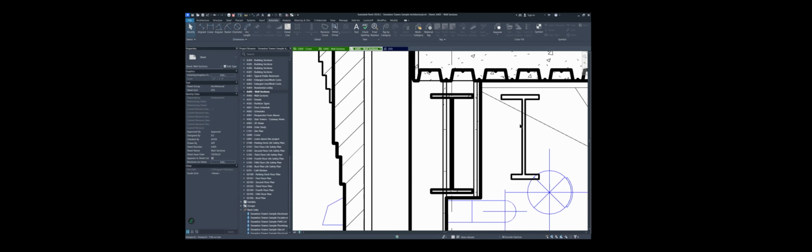So for example, let's say I wanted to put in this I-beam. I could put in a 3D model of this I-beam, or I could draw this I-beam using detail line, as you guys said. So I could go to detail line and literally draw an I-beam. This I-beam is not a 3D object, it's just a 2D object that lives only in this view. But then why draw this I-beam when I have a detail component of multiple versions of I-beams?